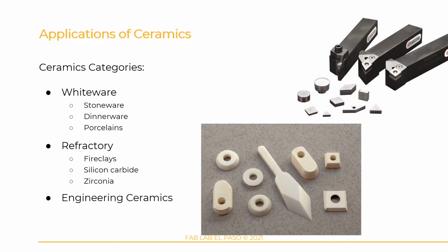Engineering ceramics are also called pure or fine ceramics and include man-made ceramics that have enhanced properties. Because engineering ceramics are superior in heat resistance and strength, they are often used as cutting or machining tools. These cutting tools do not retain heat, allowing them to work at high speeds. They are used to cut materials like cast iron and nickel-based materials, which are often difficult to machine using other methods.